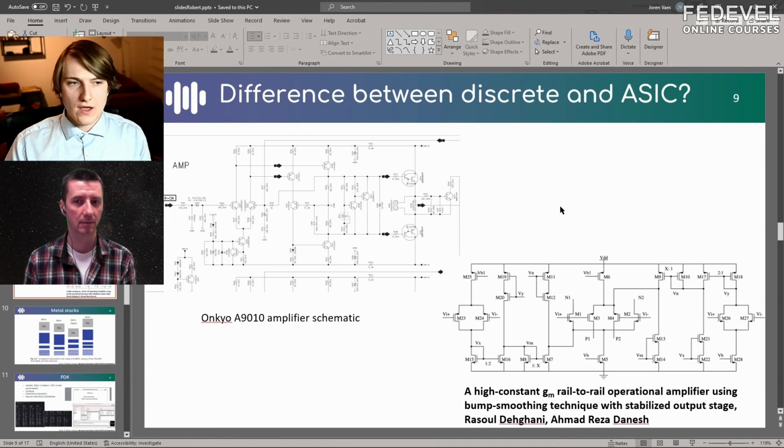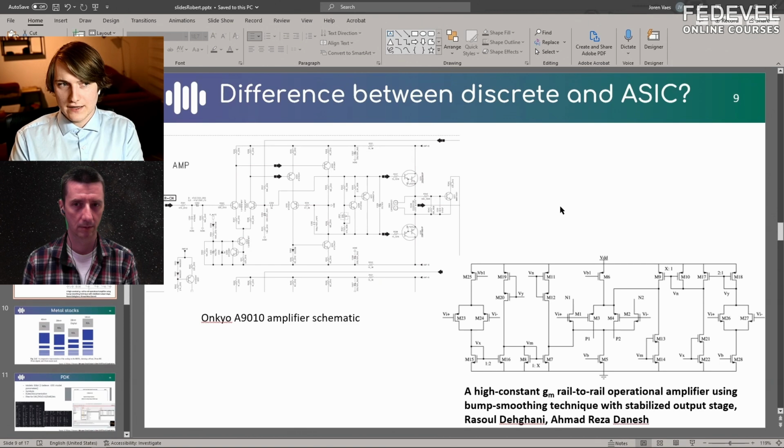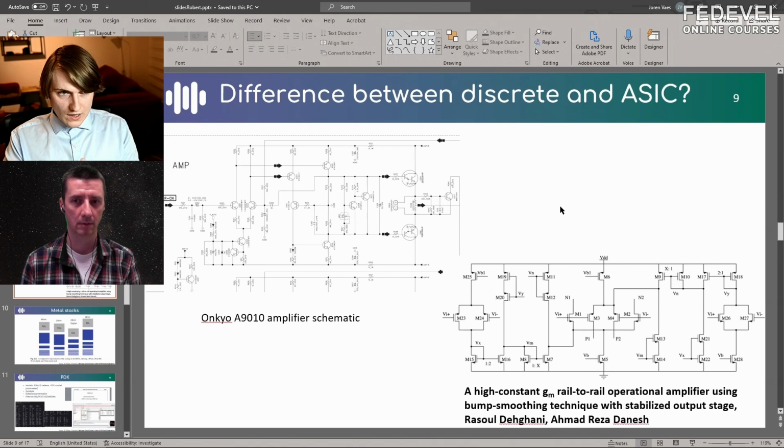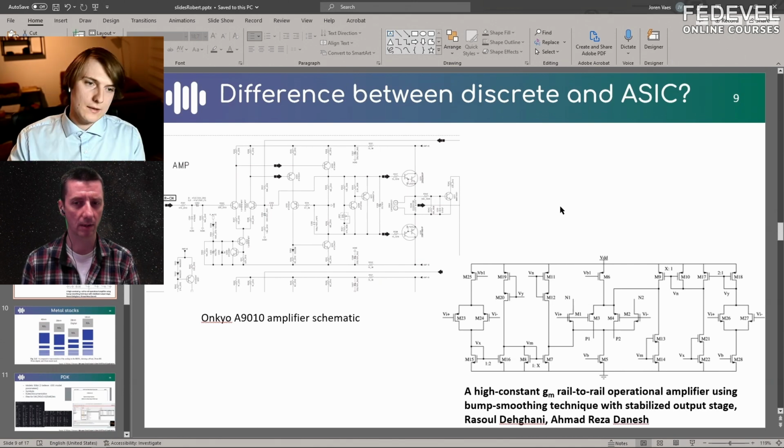For example, if you want a very precise resistor on a chip, you don't necessarily use a resistor. You could use a transistor and bias it with the correct voltage, and tune the length and width to your desired size, and then it's a resistor. You change the bias currents, the bias voltage, the size in a different way, and now it's a current source. You change it in another way, and now it's just a switch, on or off. By playing around with these voltages and sizes, we build very complex building blocks with very basic devices.